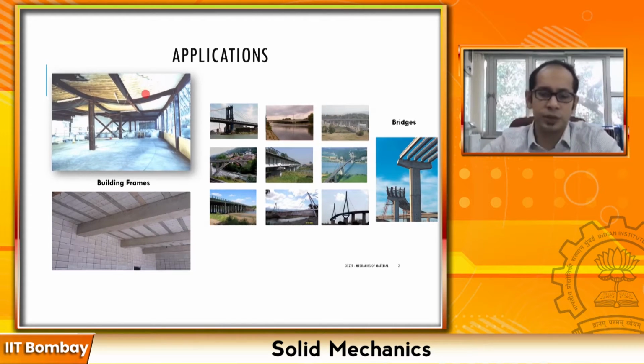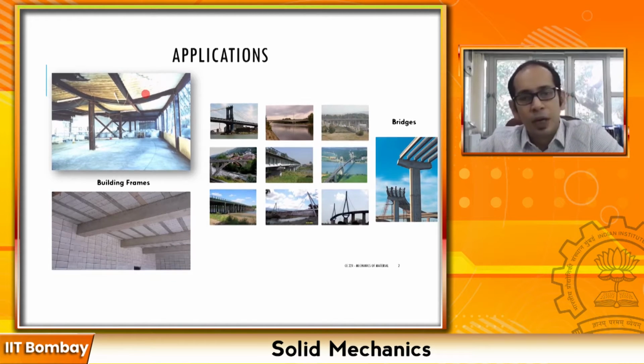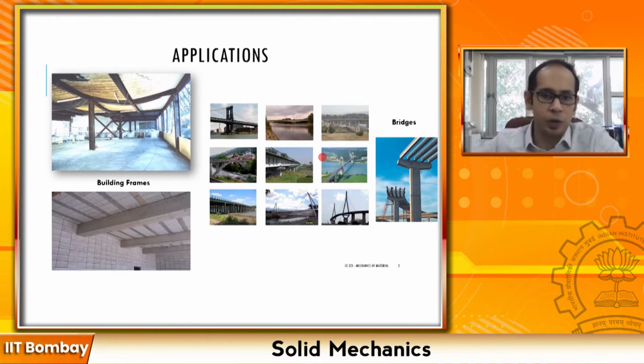And in your later courses, when you are taking concrete design and steel design, you will see that there are some limit states of serviceability which put some restrictions on how much maximum deflection you can allow in beams. Although the structure is safe, you have some perception to which you should limit the deflection of the beams, right? Now, deflections of the beams are extremely important for bridges as well, because when the vehicle is moving, you always want to have a feeling that you are moving on a flat surface. So deflections of beams play a very important role in buildings as well as in bridge structures.